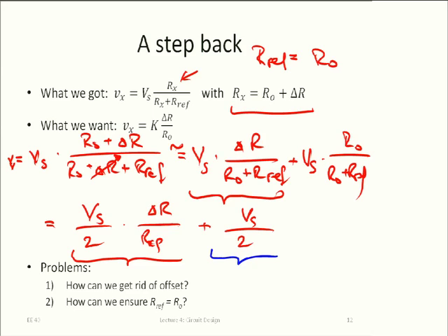Now, if we need two resistors, that's not so easy to do, but then at least we can go to the drawer and instead of pulling out one resistor, we pull out two resistors. And because they came out of the same factory, done exactly the same way, they're going to be quite similar. Also, if the temperature changes, lo and behold, resistance changes. But if they're made out of the same material, then those changes are going to track also.